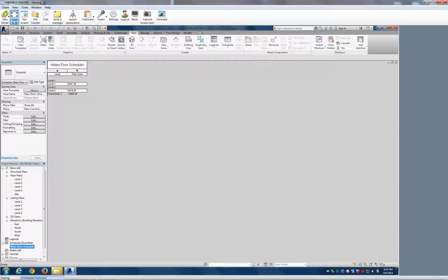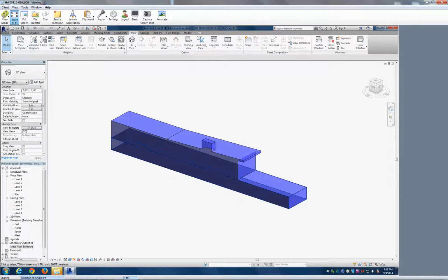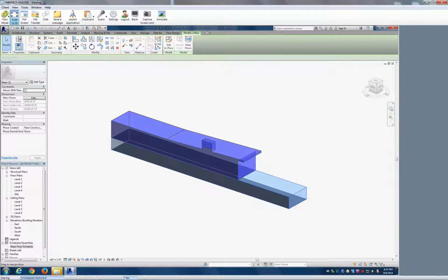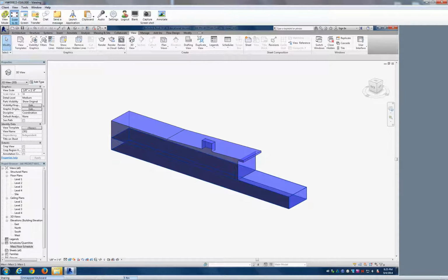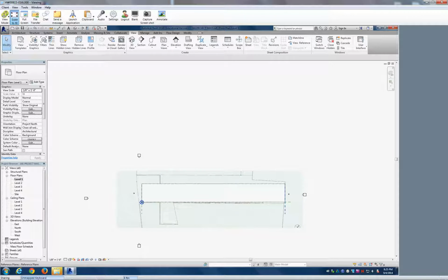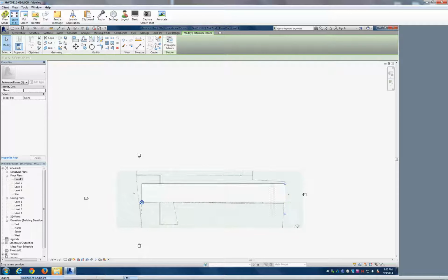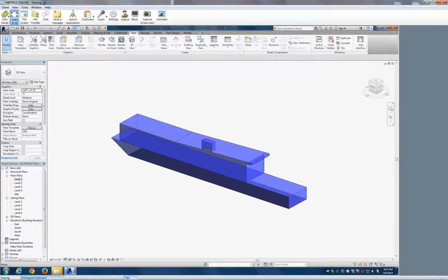Okay. So the total square footage, what's great now is if we come to our model and start manipulating our model, these numbers are going to update. To show you that, I come to the 3D view, and then I come to this model here, and I push this thing in. What does it have there? Oh, I think it's all, okay. In this case, I can't do that. This has been locked to all the reference lines, so I need to go to the reference plane and move the reference plane. So after I move the reference plane, that's what happens. So I picked the wrong side.